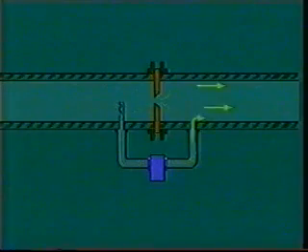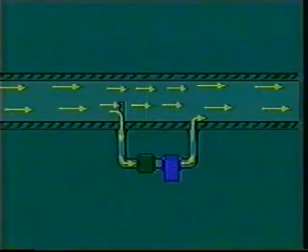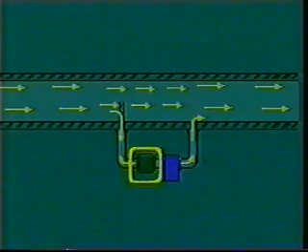The slipstream densitometer requires a pressure drop for liquid to flow through it. Commonly, an orifice plate is specially installed to create the pressure drop for the densitometer. Another device used to create flow through the densitometer is a pump in the slipstream.